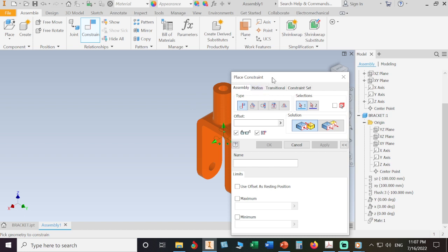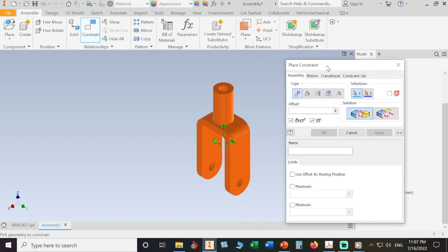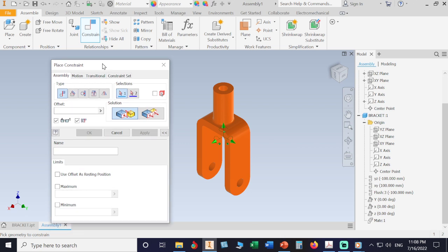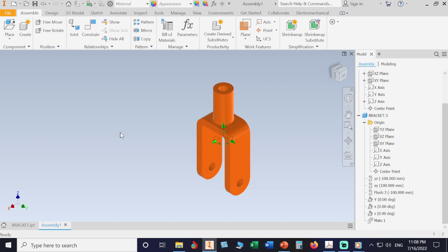We have assembly constraints, mate constraint. When we apply a mate constraint, you can mate faces in the opposite direction or flush in the same direction. That mate constraint can also mate axis with axis. Of course, we are talking about part with part. In order to create this assembly, you have to assemble these parts together to give the device, to make the device work. And we'll see this in next videos.